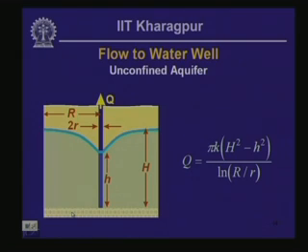Another thing you should note here is that we considered that the permeabilities in all cases are isotropic, and that is not going to be the case for fractured rock, because of the explanations that I provided in one of the previous lessons. So these expressions strictly are not going to be applicable if you have jointed or fractured rock with a joint set oriented in a preferred direction.